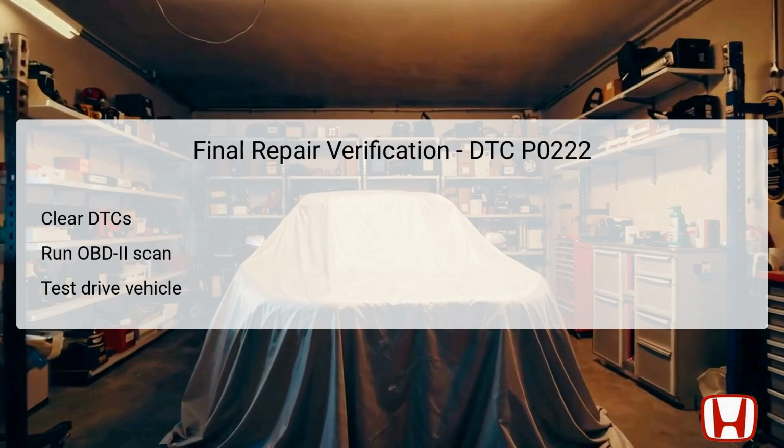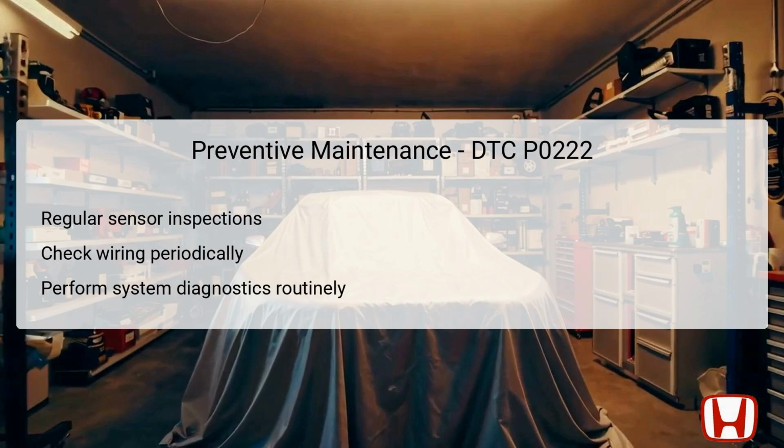Monitoring for the malfunction indicator lamp, MIL, during the test drive helps in final verification. This step confirms that the issue related to the throttle position sensor B is addressed, ensuring that the vehicle operates seamlessly on the road. Preventive maintenance is essential to avoid issues like the DTC P0222 in the future.